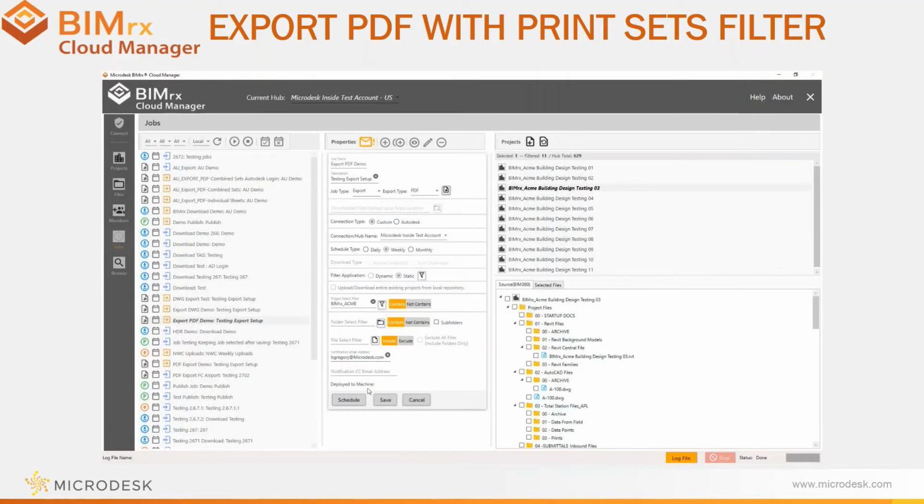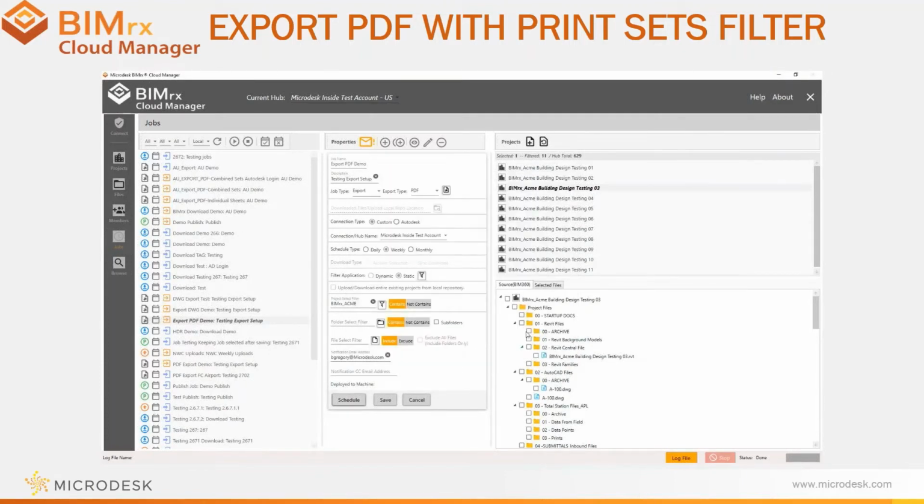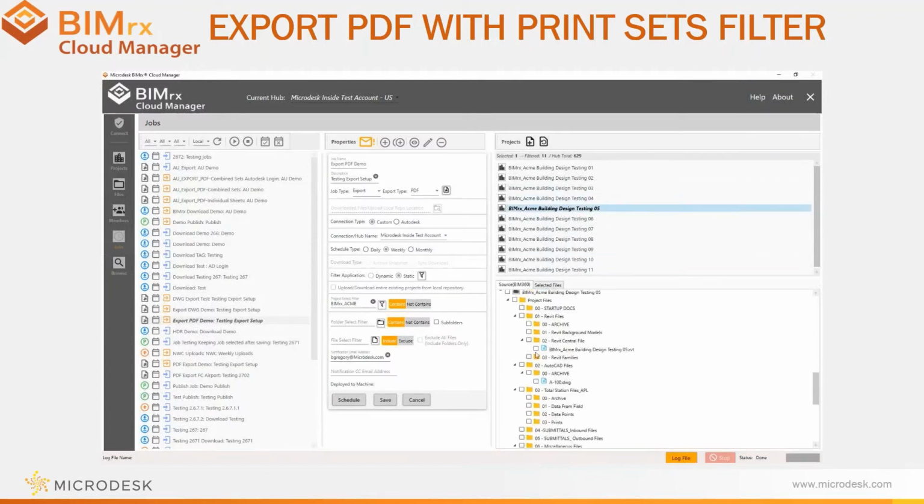Now I will schedule the job, and I'm going to have it run Monday, Wednesday, and Friday each week at 4:28 a.m. Finally, I'm going to use the static method to select the models I want to include in this export job. I add the project, and then I select a model in this project, and then I'm going to add another project and select a model from that project.